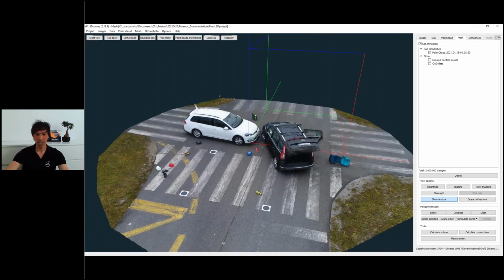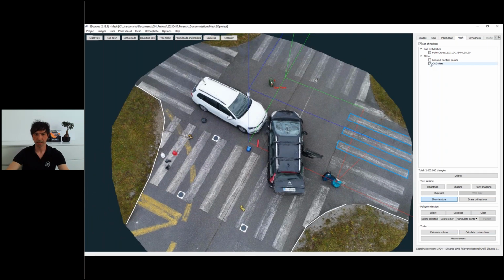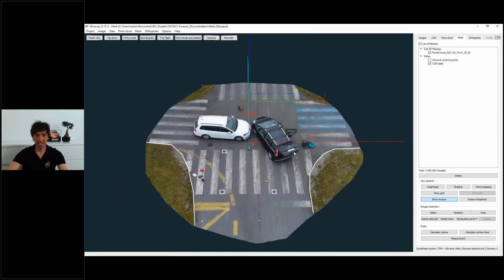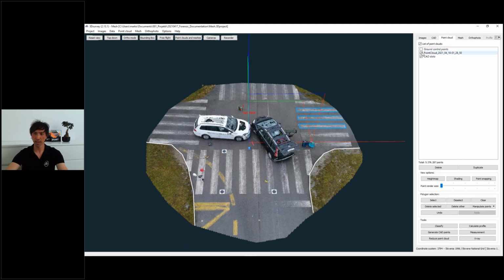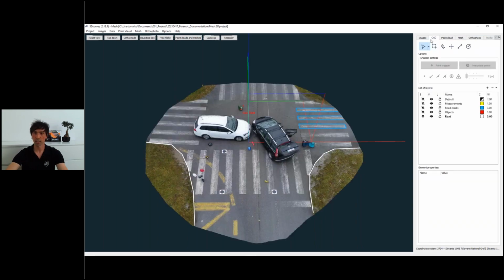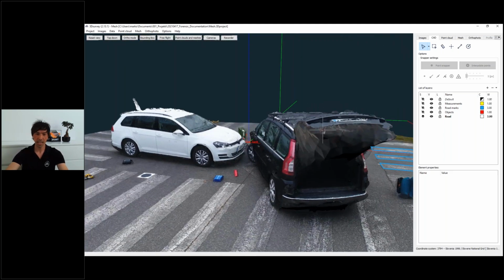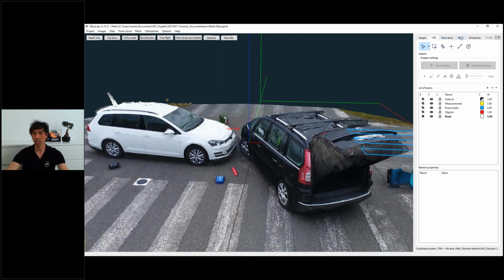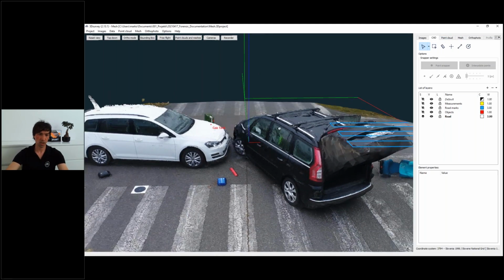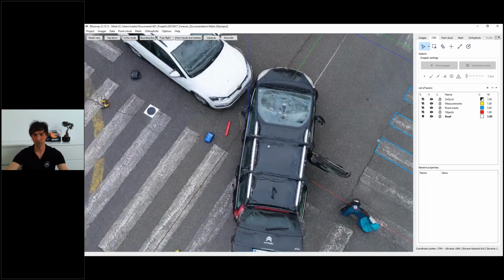And then in addition, we have here some CAD drawings. The easiest way to draw CAD lines, if you need to extract the vector data, is to draw on the mesh. That's why you can go to the point cloud tab, turn off the point cloud, so that you will have just the mesh in the CAD tab, okay? Because in the CAD tab, you actually see everything that's turned on in other tabs, okay? And right now I have just a simple textured 3D mesh.